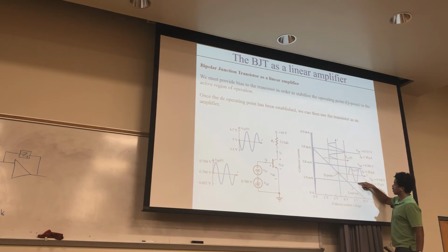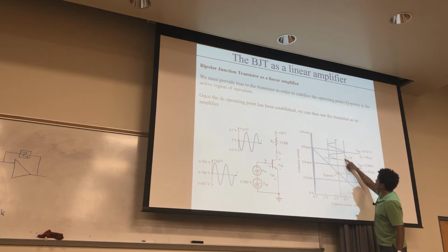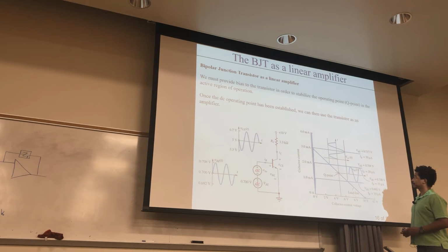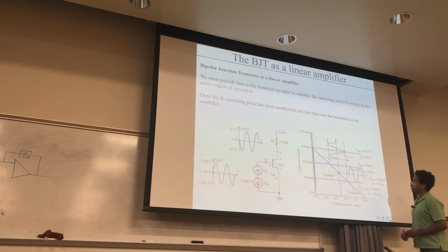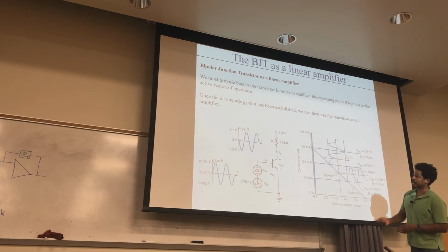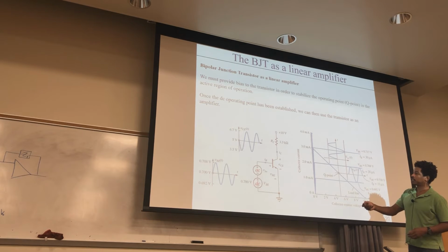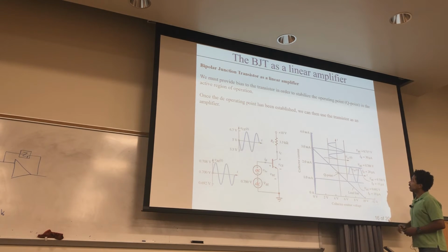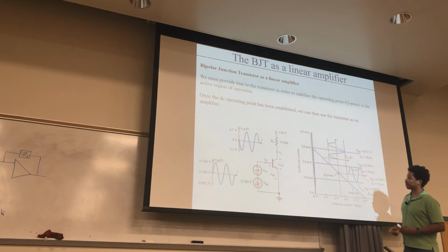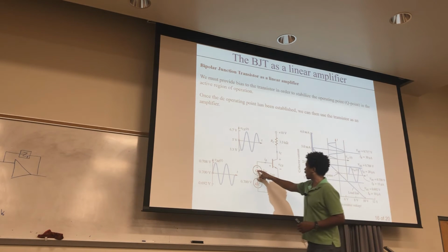And here's the lower peak, which goes to this peak. Sort of like what we've seen before with the op amps. But you have this base emitter voltage right here, which is 0.7 for the input. That's what that is for a typical Q point. It has a peak to peak or amplitude value that you have to worry about, and that's for the AC component.